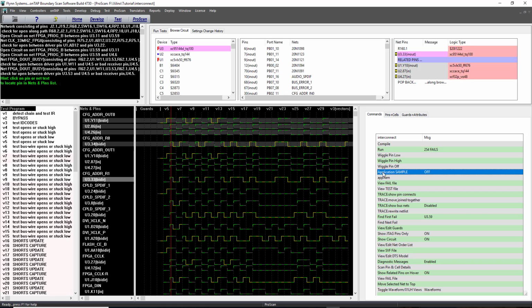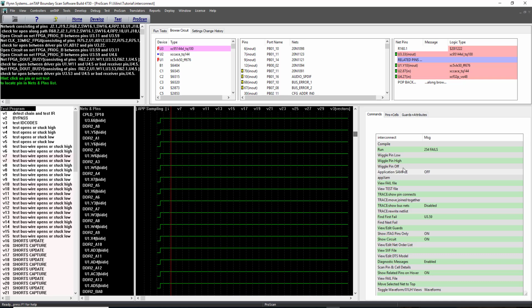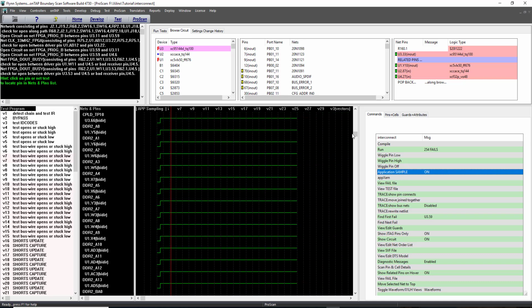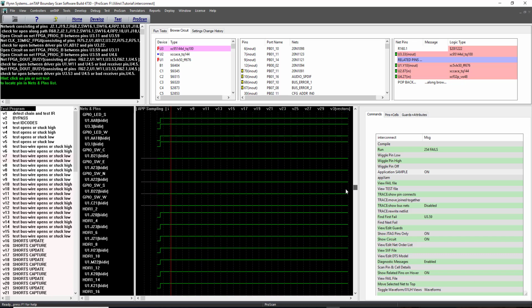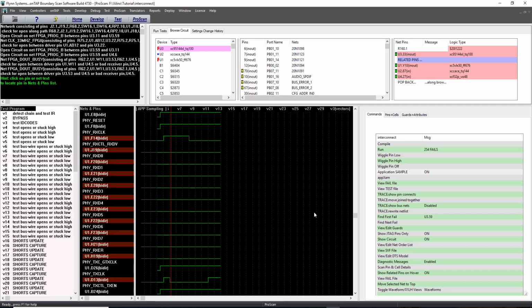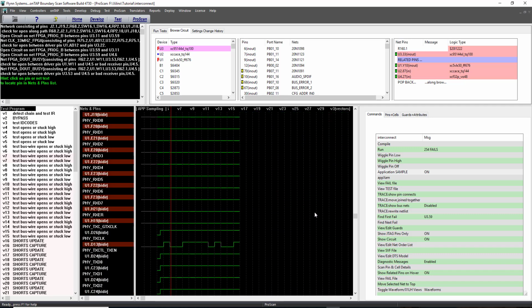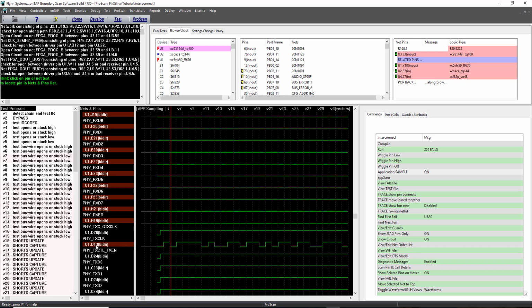We can do application sampling. Now it's actually in application mode, and if we just want to check for background signal activity on the board, we can see signals running, and we notice they're clocked. So we might want to come in here and guard these pins.